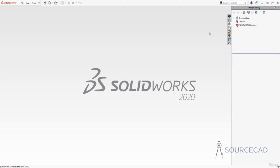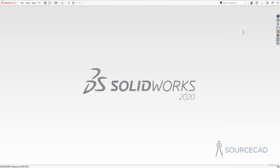We'll explore these later, but for now just click anywhere in the blank area and it will collapse to this small toolbar option. Now we have the file menu. Currently the file menu is visible, but if it is not, you need to click a push pin. So I'll just click this push pin and the file menu will disappear. It will hide under the logo. That's the way it works by default, but I've just selected this file menu and made it sticky using this push pin. So click the push pin to keep it here all the time.